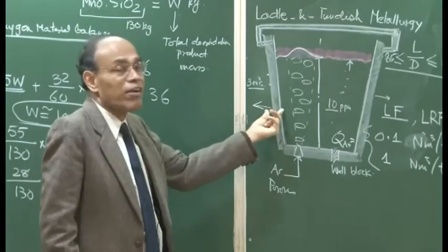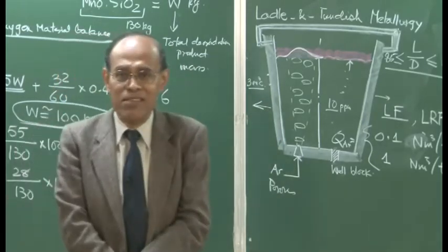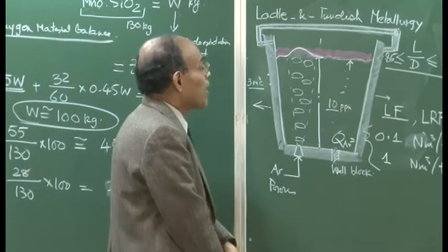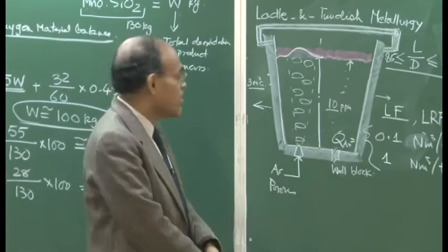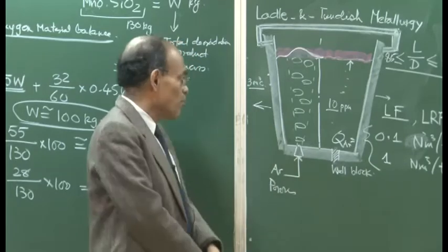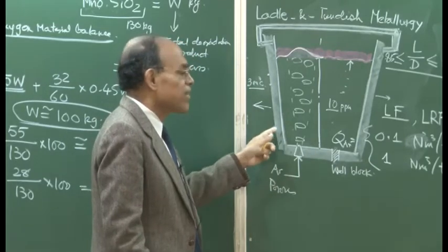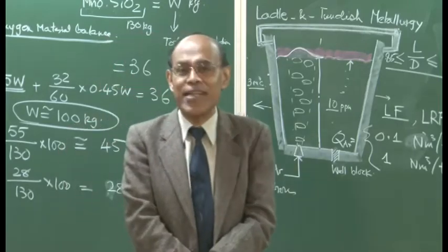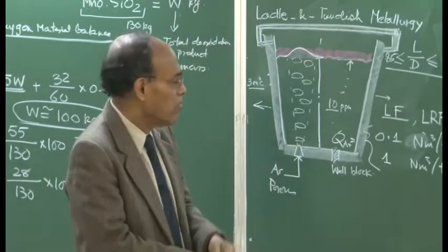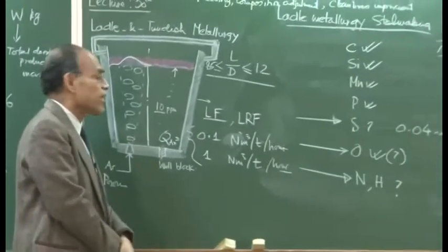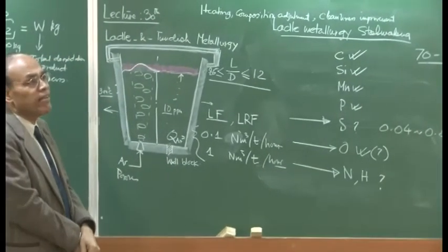And these refractories are basically basic refractories, tar bonded magnesite, mag-carbon brick, that is what typically is the name in the industry. High alumina bricks are also used by people. These ladle bricks require relining after 60-70 heats, it varies from plant to plant. There are plants which can recycle ladles for 120 heats or so on.